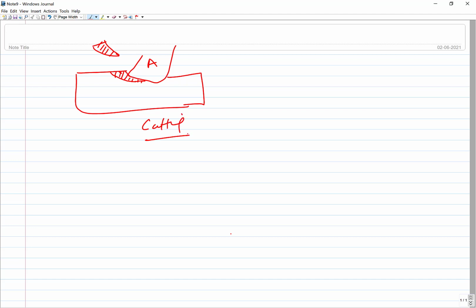But when the abrasive has been rounded off and the material is very soft and ductile, the indentation performed by the abrasive is fine, but the material flows sidewise under the effect of the stresses. So in this case just plastic deformation through the flow of the material sidewise is taking place, with no removal of the material.